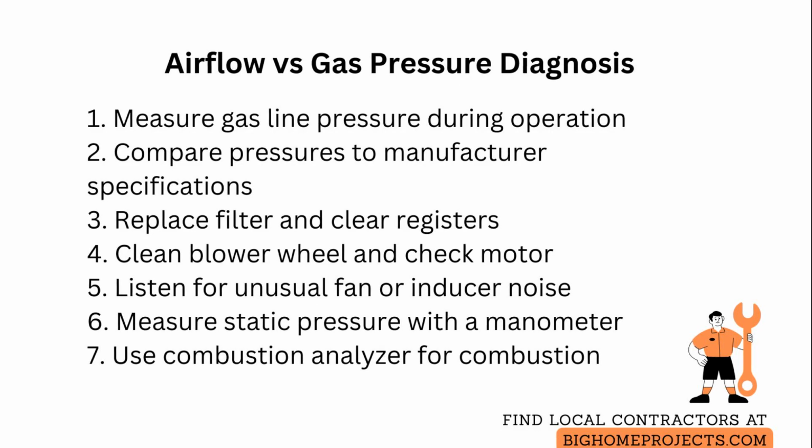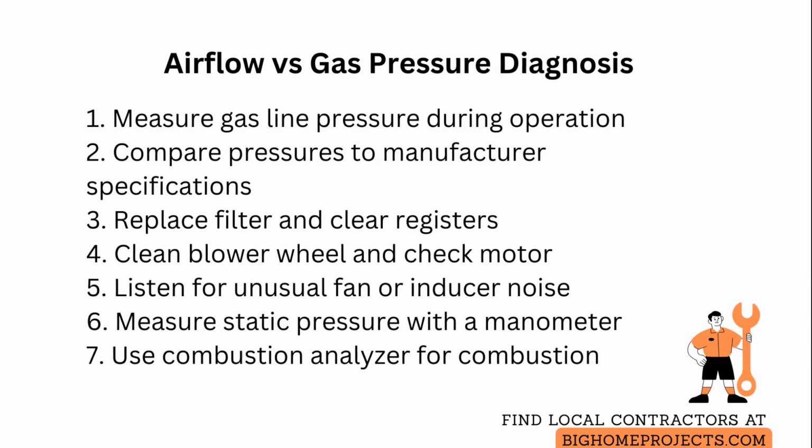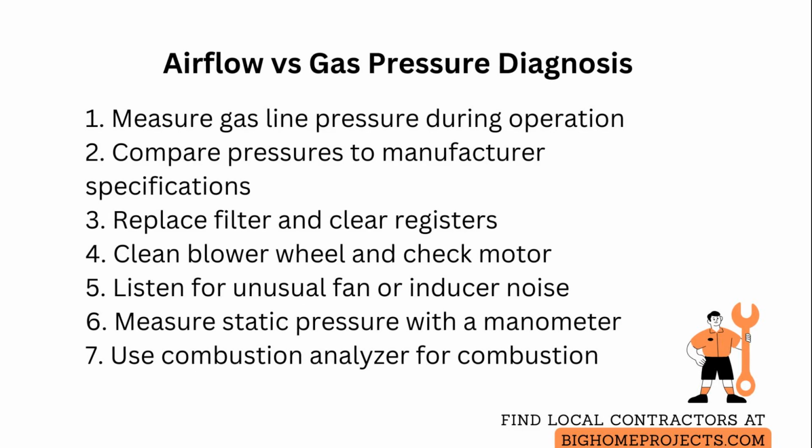Finally, if available, use a combustion analyzer to check carbon monoxide, oxygen, and stack temperature. Abnormal readings help distinguish combustion anomalies from pure airflow overheating problems.